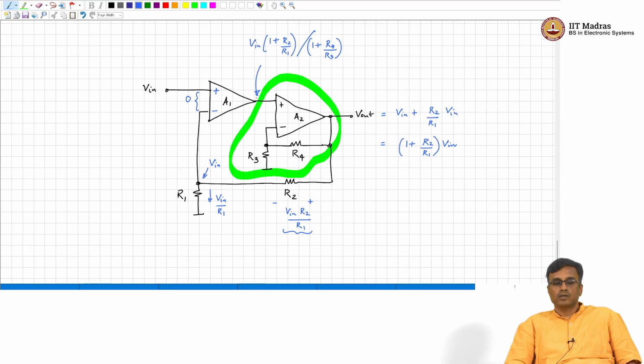All right. So, I hope you got a hang of the analysis of ideal operational amplifier circuits. Most importantly, a common mistake to make is to apply the rules of the ideal op amp when there is no negative feedback.